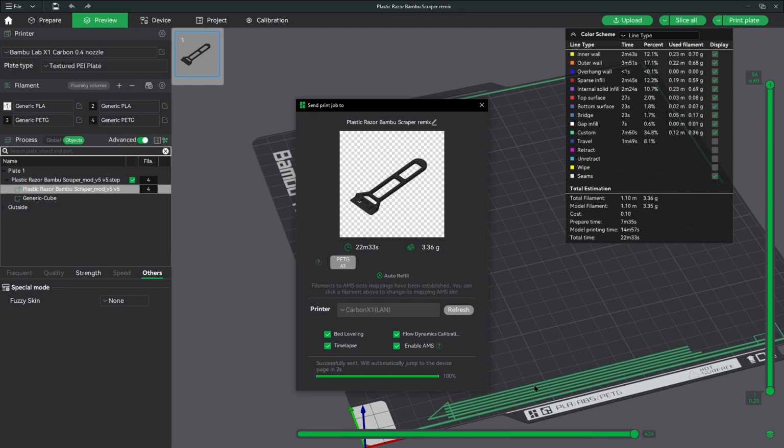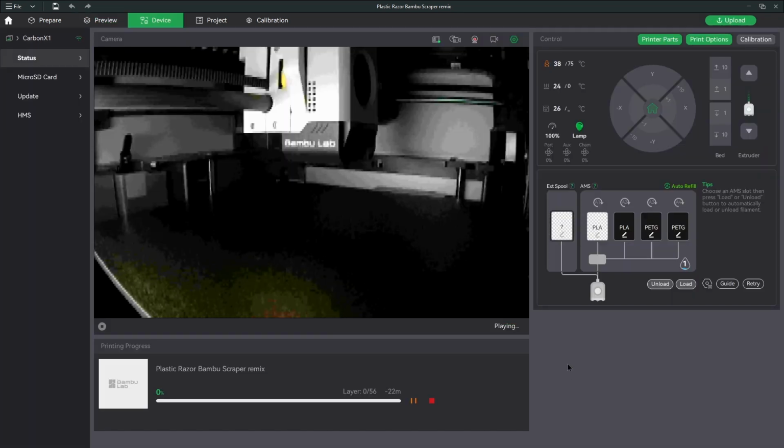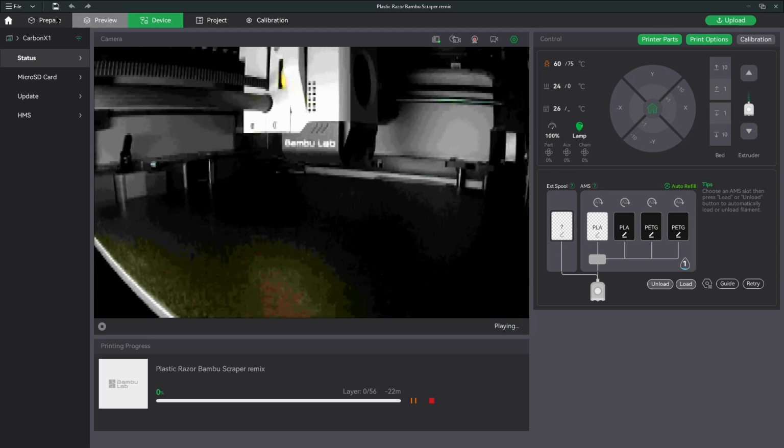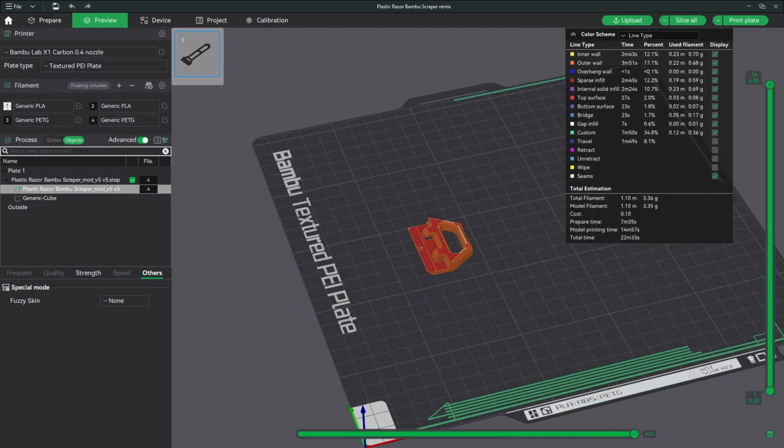Now, while that's beginning to launch, what I often do is I go back to my slice preview and look through the layers again just to see if there's anything that I missed, because I can still cancel this print because it hasn't laid anything on the build platform yet. I can still cancel the print. But everything looks good here, and through the magic of editing, we jump ahead to when the print is finished.